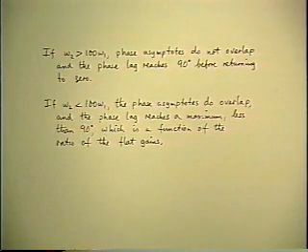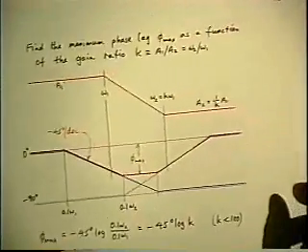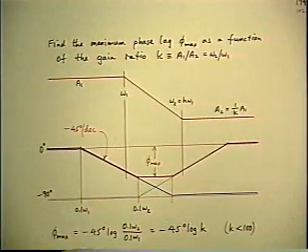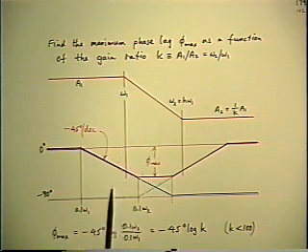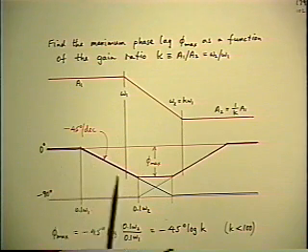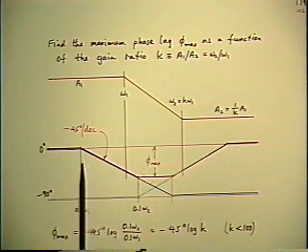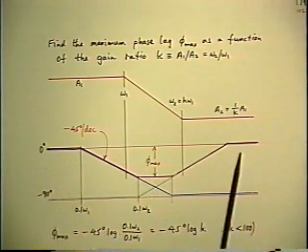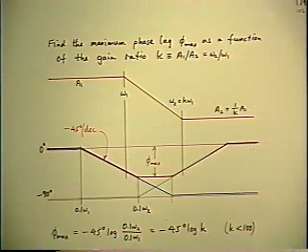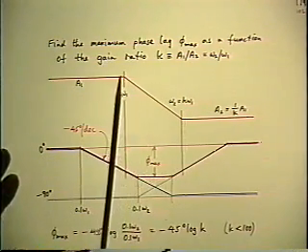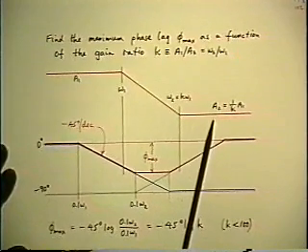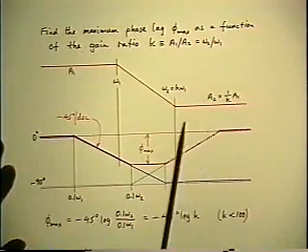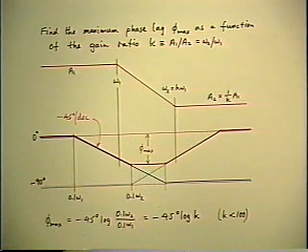And that means drawing a new picture. In the case of an overlap, you'd have something that looks like this. And this is a very common circuit. It's called a lag lead circuit for obvious reasons. You get a phase lag followed by a phase lead, and the significant feature is that you get zero net phase change from zero to infinite frequency. You start at zero, you end at zero. The gain, however, has dropped off from one flat value to another. This is the reason why this is a common circuit.